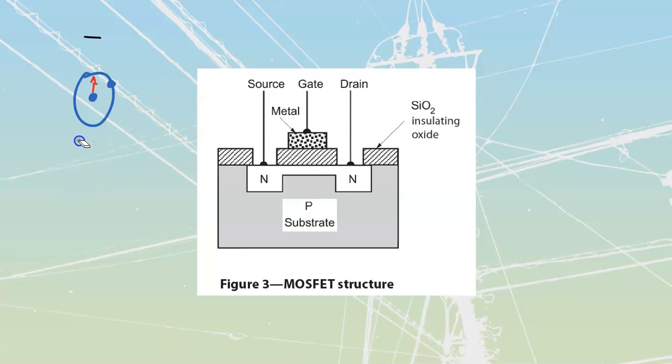These are a lot more electronic type of things than what you're probably going to have to ever deal with as an electrician. But depletion modes versus enhancement modes are going to allow me to increase the size of a channel. So I can start with a channel that's a certain size, and I can basically drop the depletion region, which is going to enhance that channel, make it bigger. Depletion mode means that I start with a channel and I can only make that channel smaller. I'm also going to have a couple of them that I can operate in either enhancement or depletion, which makes them very handy for semiconductor applications, because I can either throw a gate wide open or I can completely close it off for the most part.